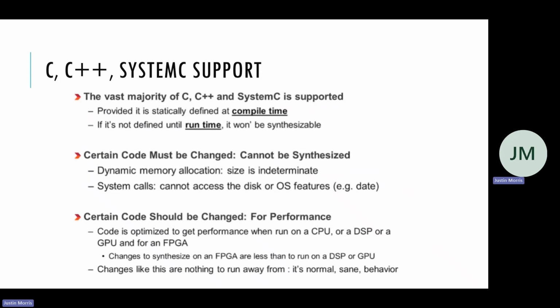If you are targeting an ASIC design or an FPGA design with the HLS tool, like we talked about at the beginning, you do not just give it the C code that is the baseline. You need to change the C code and recode it in a structural way that is optimal for the HLS tool to give you a better design.